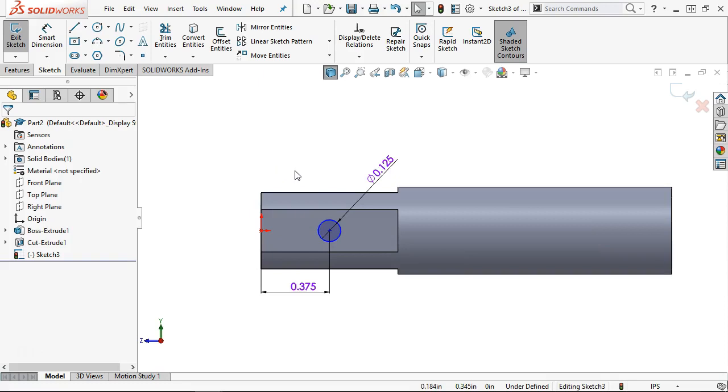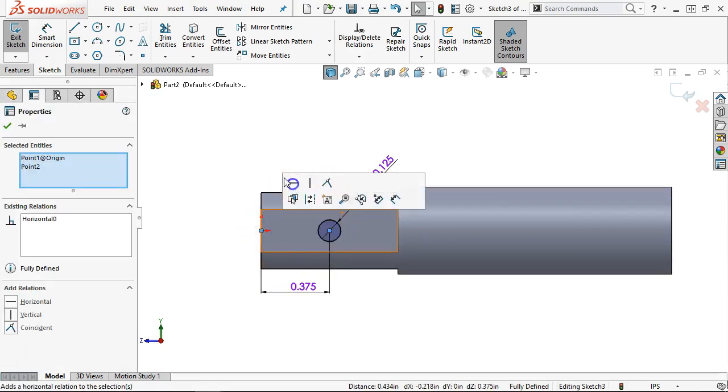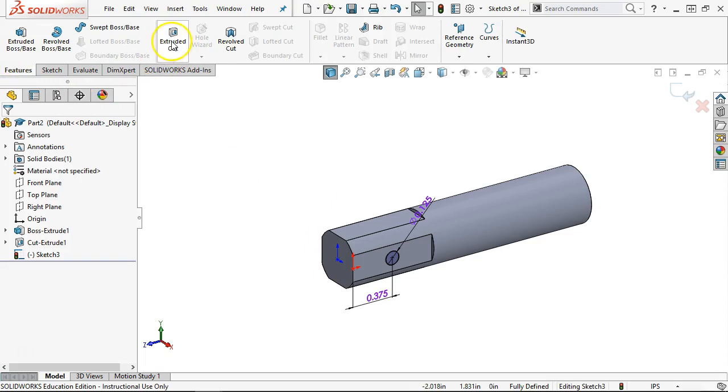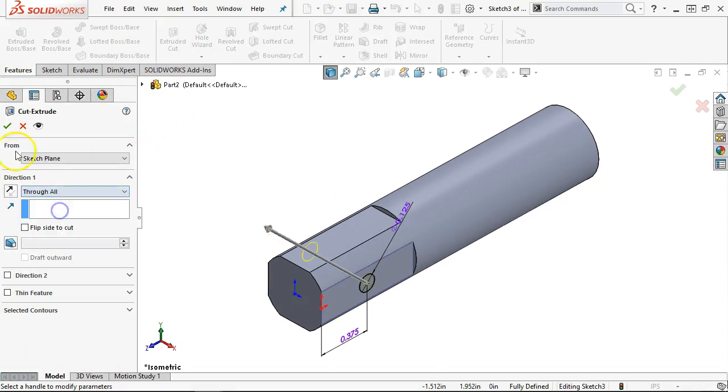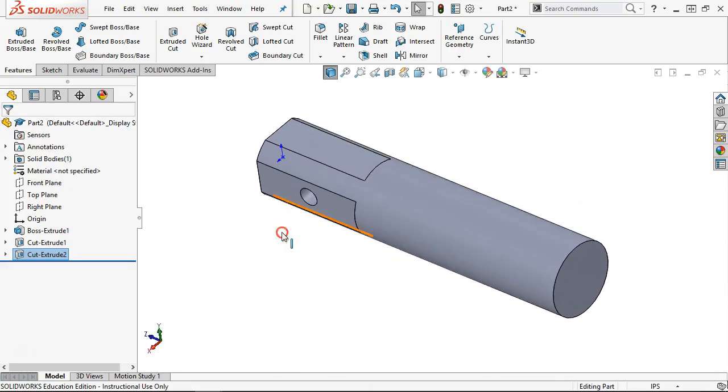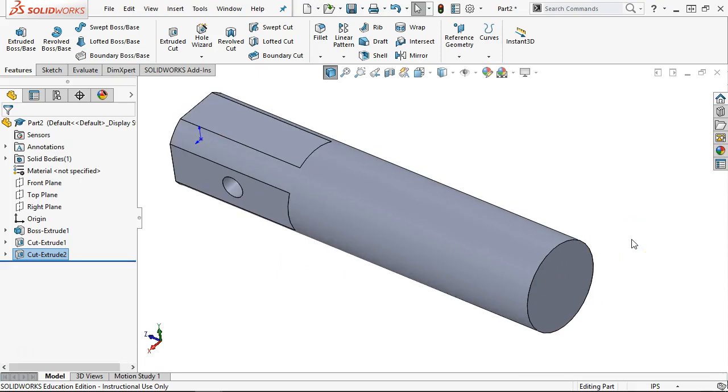If we're making these in any kind of production, we need to account for a little bit of clearance on the depth of our notch, and allow for some variation so that we don't really want to drill every one of these in place. At least I don't. Okay, so through all, and we'll set for the pin. All right, I do want to create a call out for the thread, and the thread designation was the 1/2 inch 12, and its length.